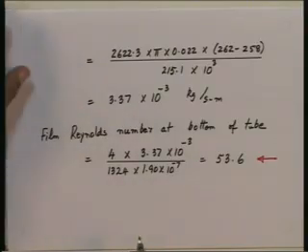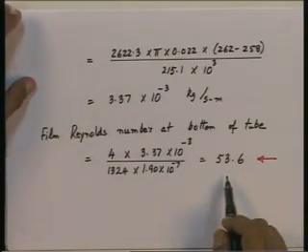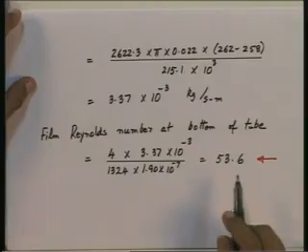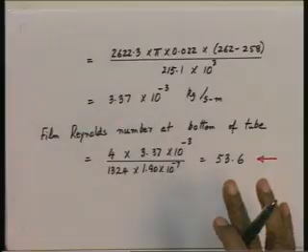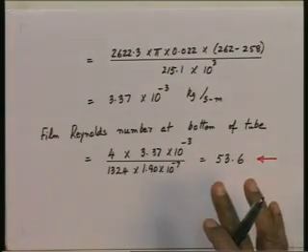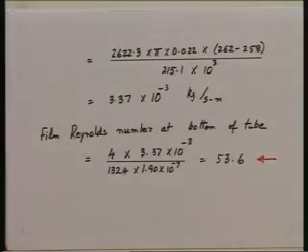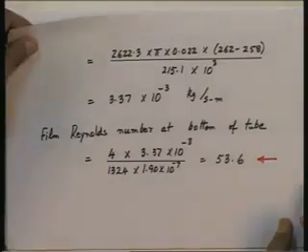It is possible, because the film Reynolds number at the bottom is more than 30. 30 is considered a kind of a dividing line. Up to 30, we get a very smooth interface. Above 30, one finds that ripples tend to form on the condensate film surface. So, this is one comment which you may want to note at the end.